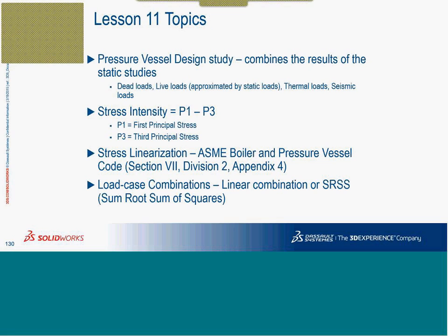Pressure vessel study also does a combination of results of multiple things, but the way the load case manager handles it is very different. And the important application, as per the name of this study, is towards pressure vessel design. And we put it in a very specific way. This is what it's all about. Stress linearization is what it does, as per the requirement of the ASME boiler and pressure vessel code, section so and so. So this is what it is.